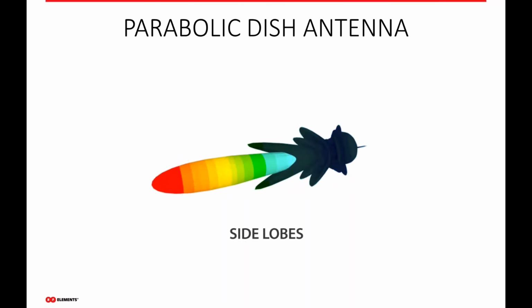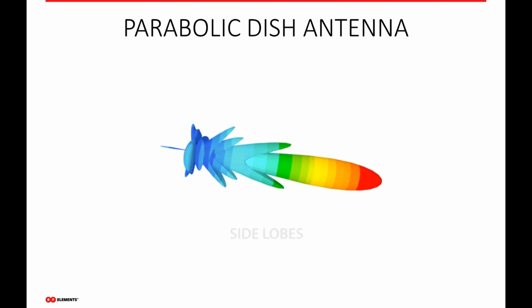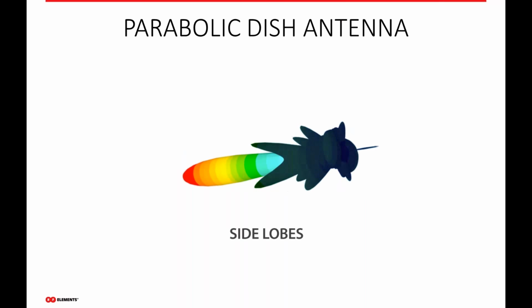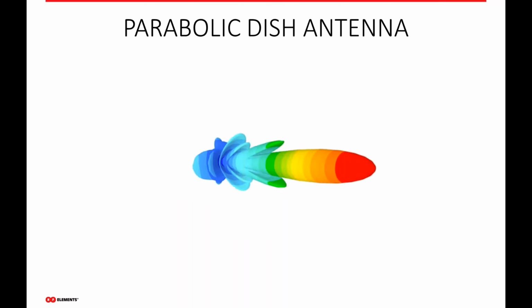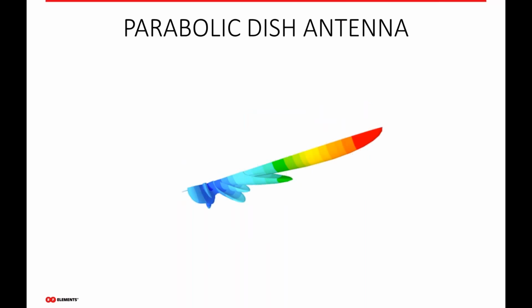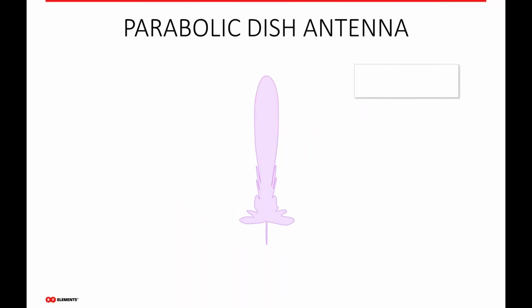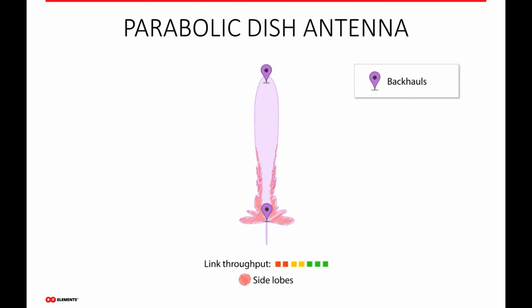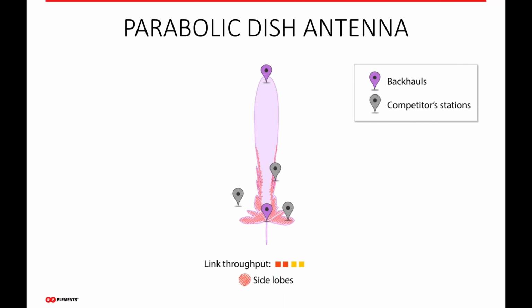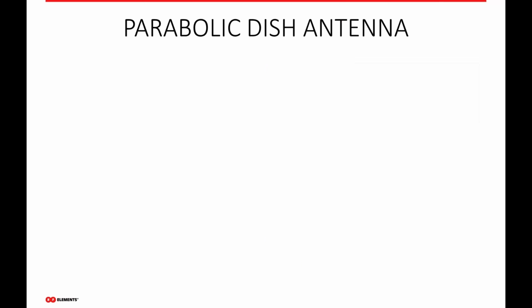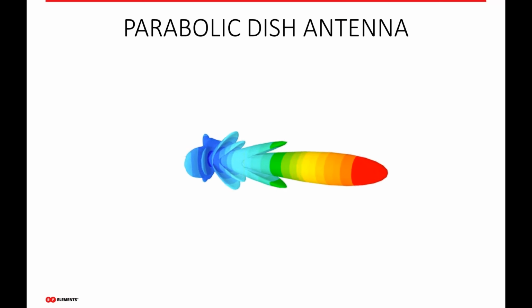If we look at it in 3 dimensions, again, you can see the highlighted areas are the side lobes. The side lobes are any secondary lobe outside the primary main lobe, right? So all these lobes send and receive signals to areas. So again, in the standard point-to-point, you're typically thinking of that main radiation beam angle as if that's the only part of the antenna that's actually working. And if we look at the side lobes, they really start creating issues.